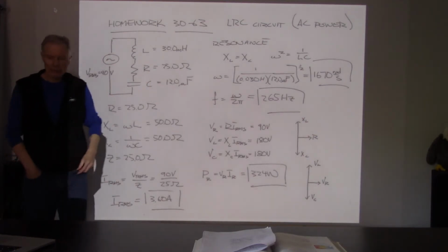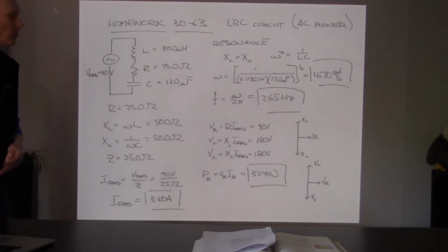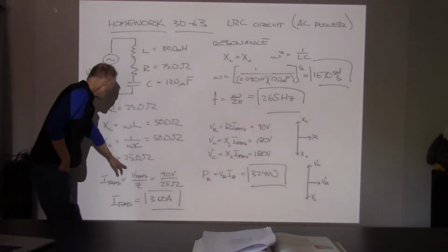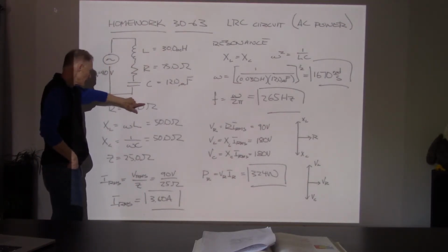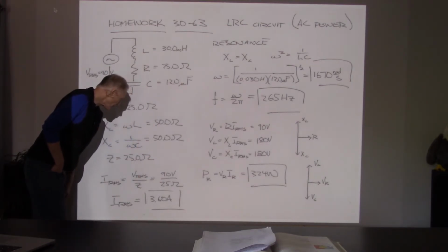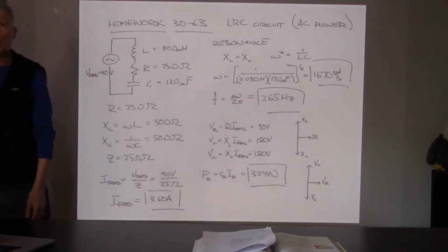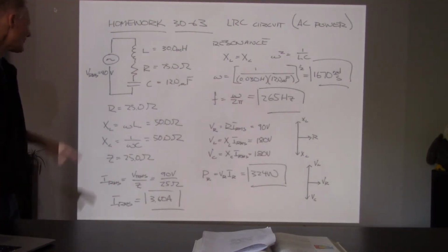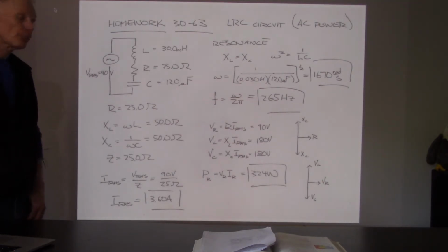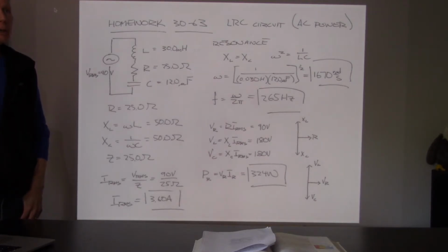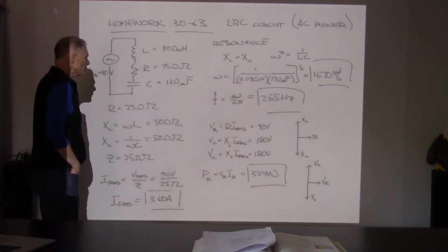And that depended on the frequency. It's just that one frequency at which they'll exactly cancel out. So that says that I can take my VRMS, divide through by my Z, which is now just R, 90 volts divided by 25 ohms. That gives me 3.60 amps. Everything here was in average values and RMS. So 3.6 amps is my RMS current value for that.